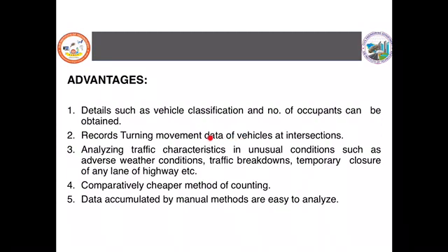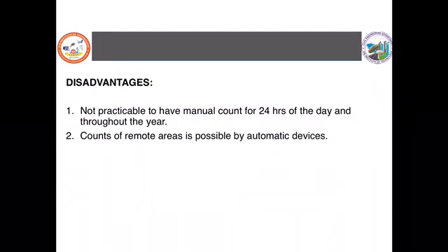And also we can analyze the traffic characteristics in adverse conditions, such as any breakdowns or temporary closure of highways, that can be noted physically there. Also, this method is comparatively cheaper compared to the other automatic counting. The data accumulated by manual counting is easy to analyze.